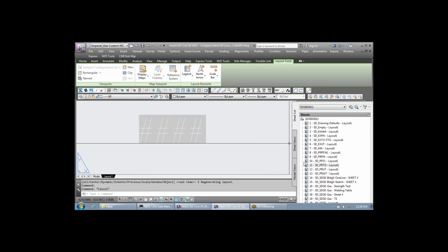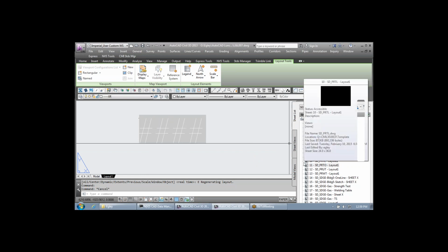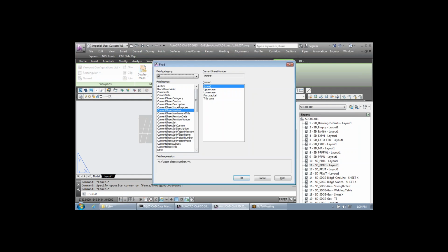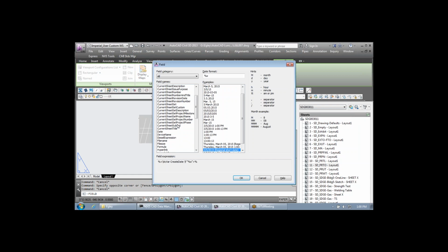Padma took it one step further. She actually had match lines reference that said +1, -1. Yeah, you definitely do that. Took care of all the match lines and took care of every reference that we did. You can add custom properties into these fields as on the ones that Jarrod just showed. And then you can add, this is the begin station for that particular sheet and the end station. And then when that changes, it gets automatically updated. Which it did. Multiple times.